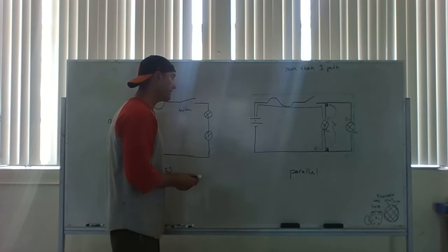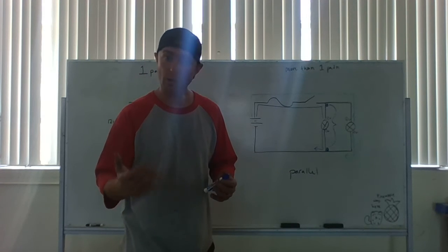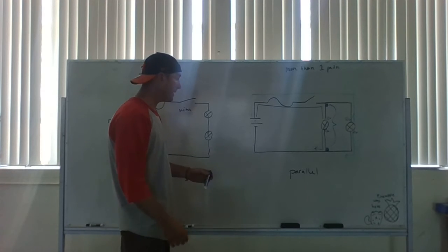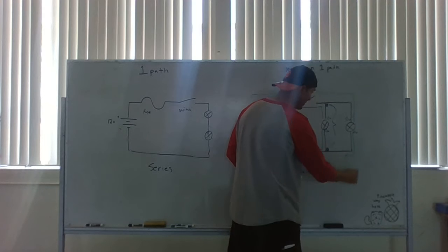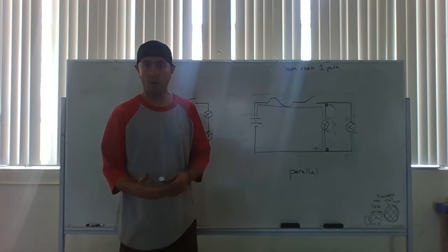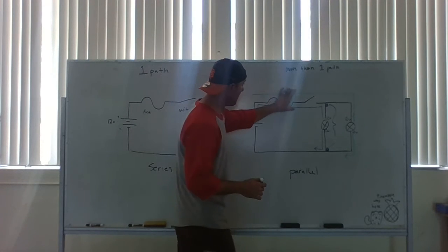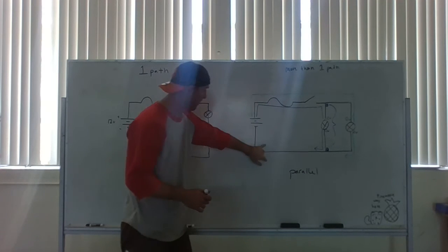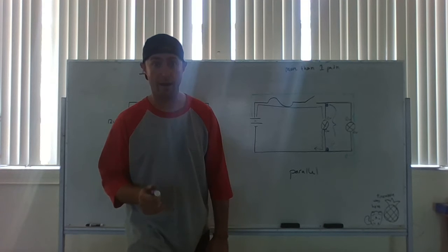Now on the opposite side, if both are not working, that also shows me a lot. If they're both out, that means the problem is not in the load section of my circuit, because they're wired in parallel. The only way I could lose both of those lights is if some part of my power supply is not working or some part of my ground path is not working, and there are even ways we can check for that.